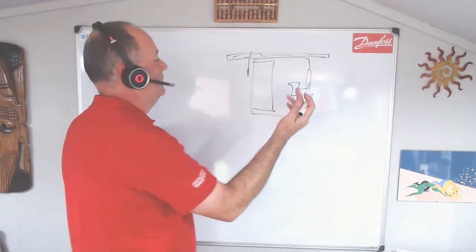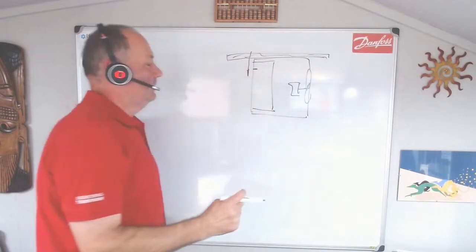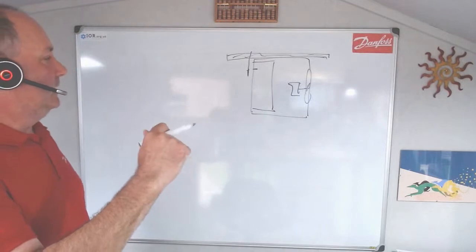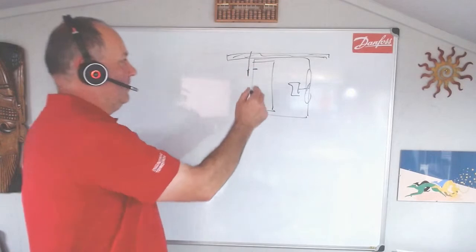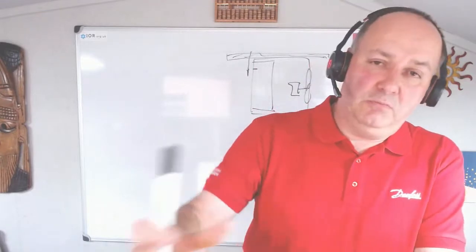The way I was taught was basically to actually put it in the coil, so it's sensing the right temperature. The other thing to say is that the defrost termination probe needs to be in the area where the ice lasts the longest. And this is very much site specific, application specific, depending on the airflow across the evaporator. All these things go into that discussion.